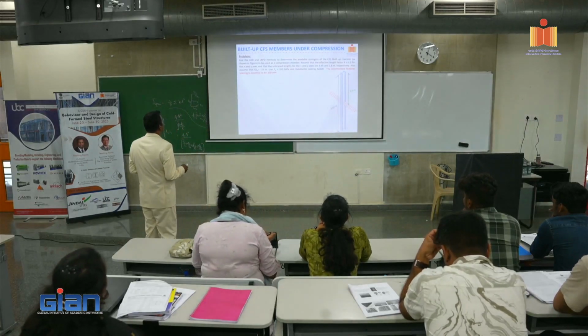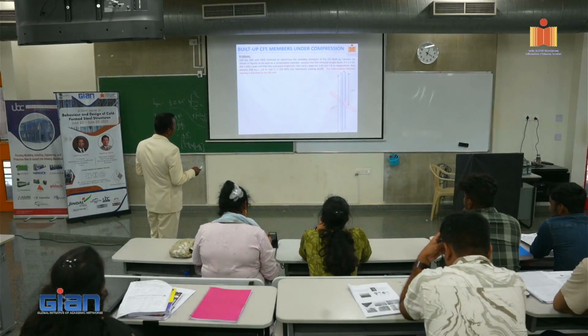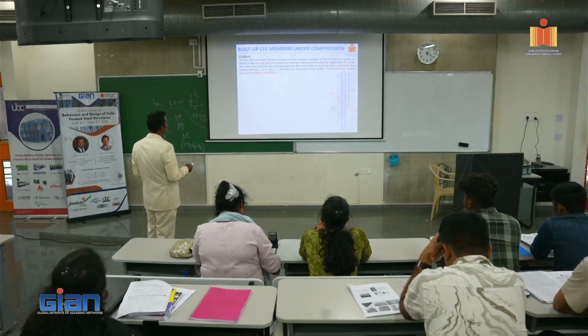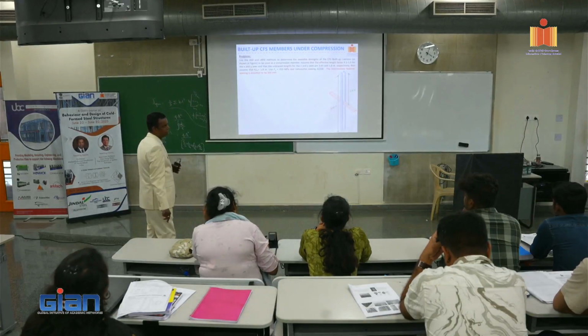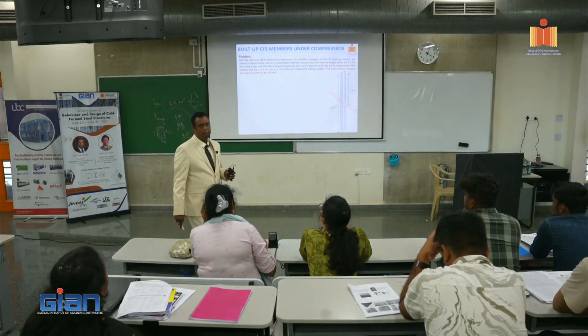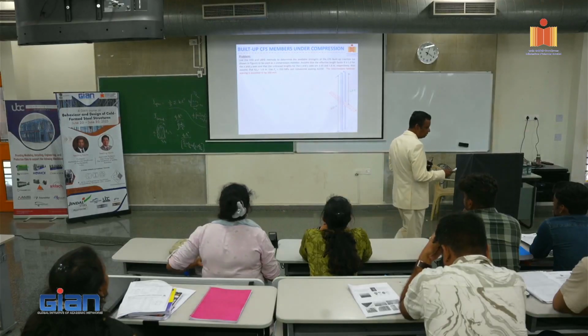And use Fy equal to 350 MPa and galvalume coating as AZ 200. The intermediate fastener spacing is assumed to be 300. So we are putting some fastener spacing that is going to be 300 mm. So every 300 mm there is some kind of a restraint that you will have. Right? Any questions on this one?